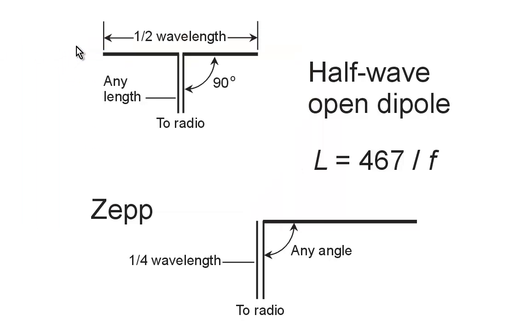Well, when you actually build a wire antenna for 7.1 megahertz and decide to string it up, say, between two trees in your yard to operate on the 40-meter ham radio band, just an example, 40 meters being the 7 to 7.3 megahertz United States ham radio band, you're going to have to trim the antenna.